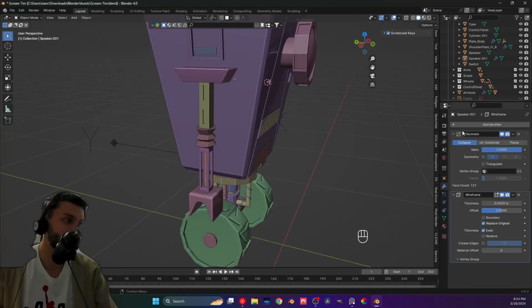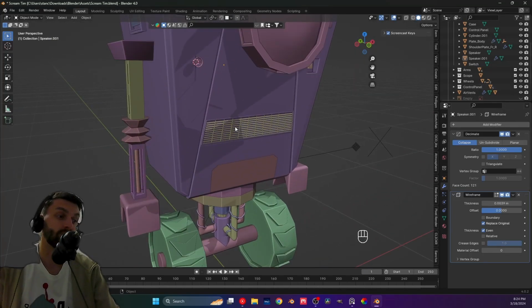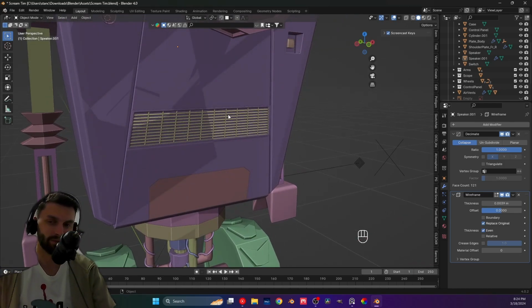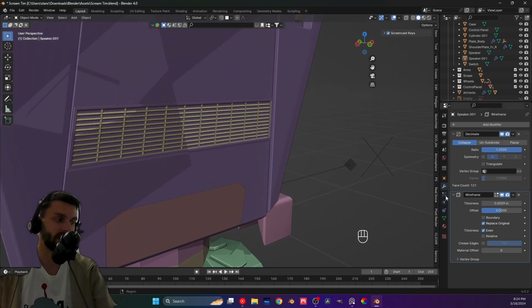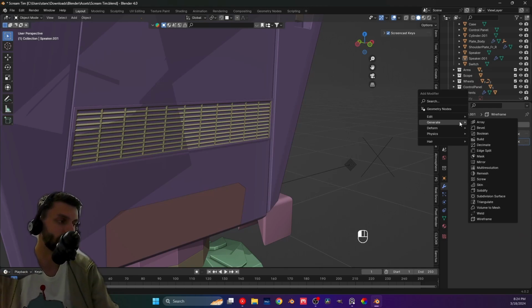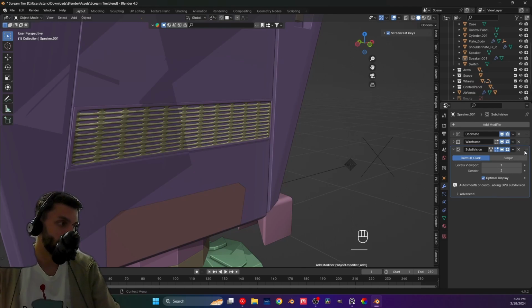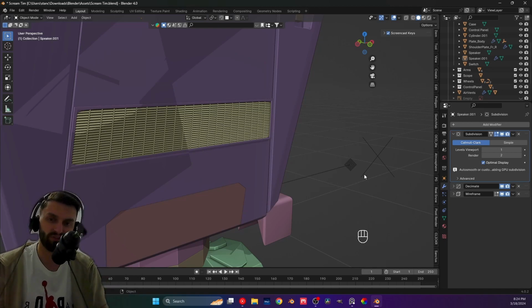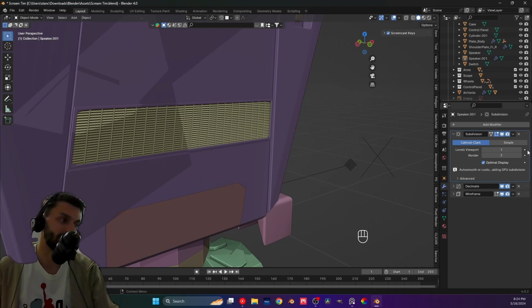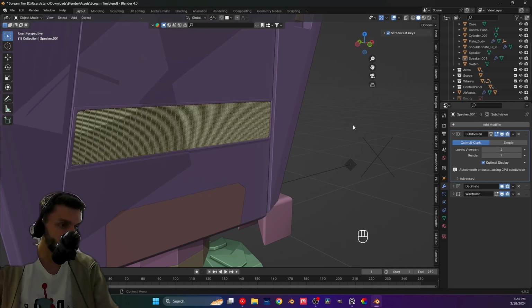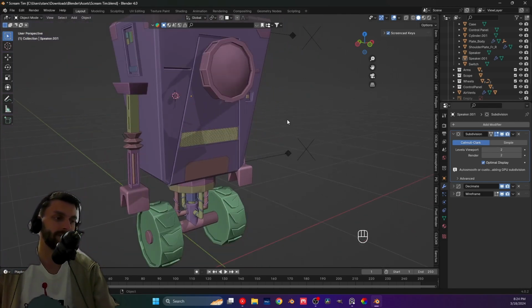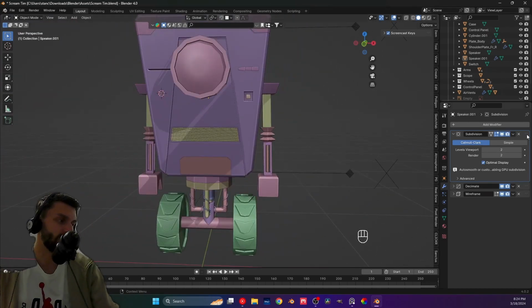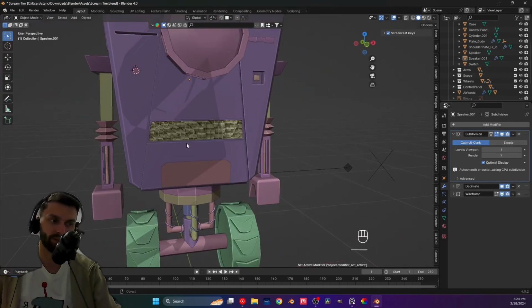But again, to make that grid look even better, which we can do, it will increase your geometry. So if you want a higher poly character, you can do it. I will probably not. But what you gotta do, and it's what I found from ChuckCG, is you can add a subdivision surface before you do the decimation, which makes a lot of sense, because the subdivision will add even more geometry on top of what you already subdivided back there. And you can just keep increasing it, and that will make a better grid, which definitely looks better. But again, it will also increase the geometry.